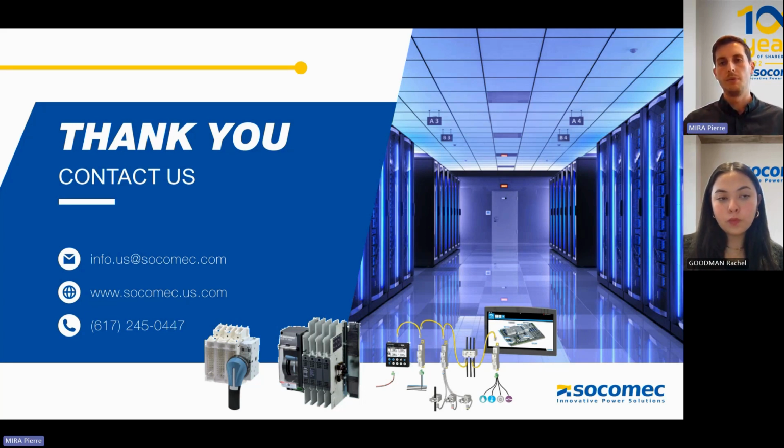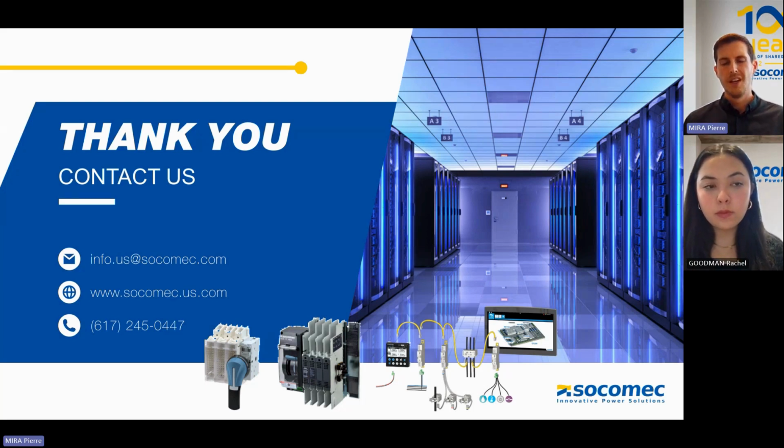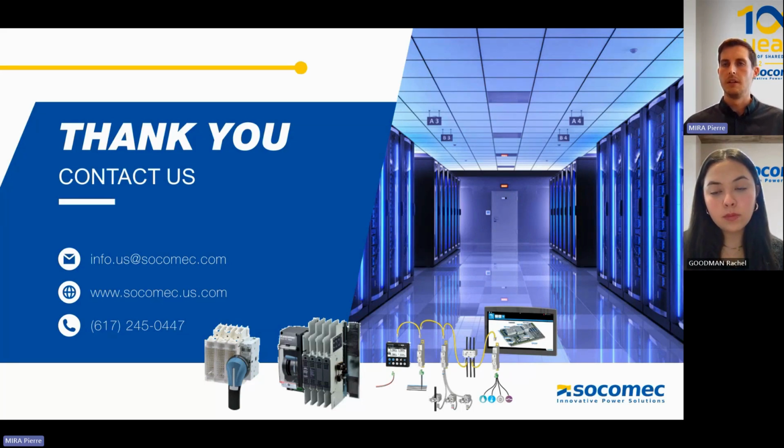For example, we see a lot of 500 kVA PDU powered by a 600 amp static transfer switch, or 1 megawatt PDU powered by a 1200 amp static transfer switch. So at this moment, I would say the most popular ratings in North America are the 600 amp static transfer switch and the 1200 amp static transfer switch.